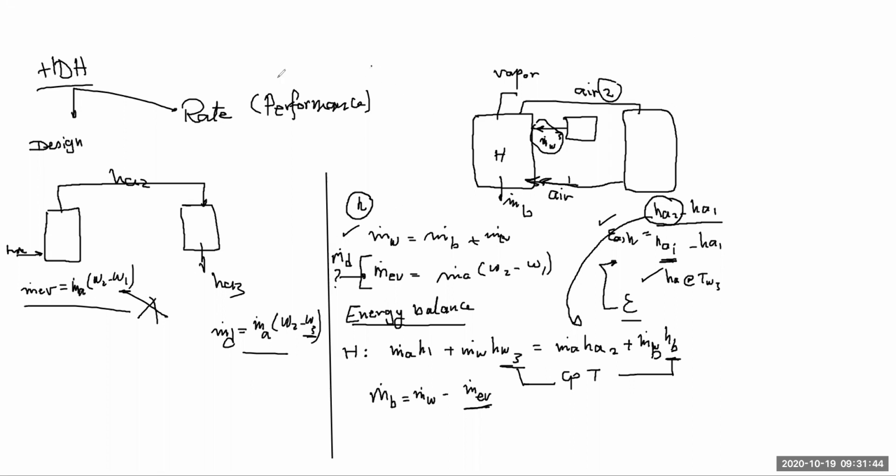Yes, Doctor. But again, you said there is no difference in the expression of the effectiveness. As long as I'm talking about a water heating cycle, and the water enters here hot, and the air enters cold, then the effectiveness is not going to change, whether it is an open system for the air or a closed system for the air. Water is hot and air is cold. So always the effectiveness is going to be this expression here.